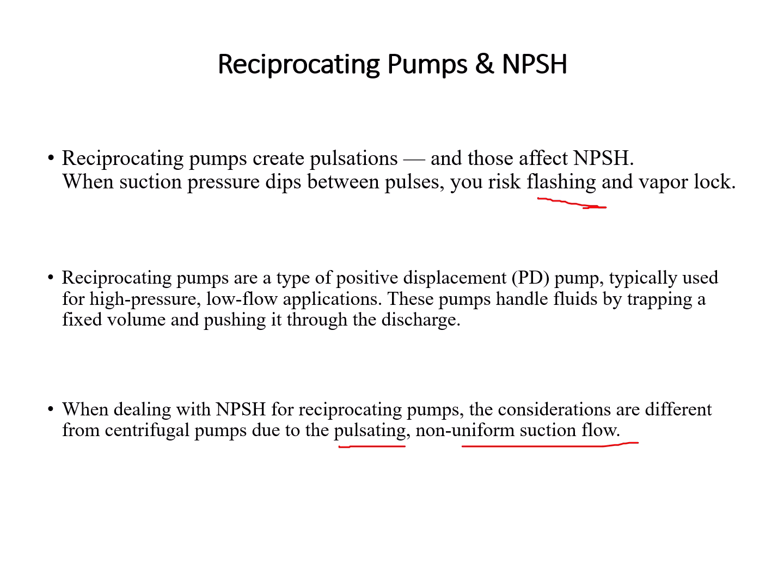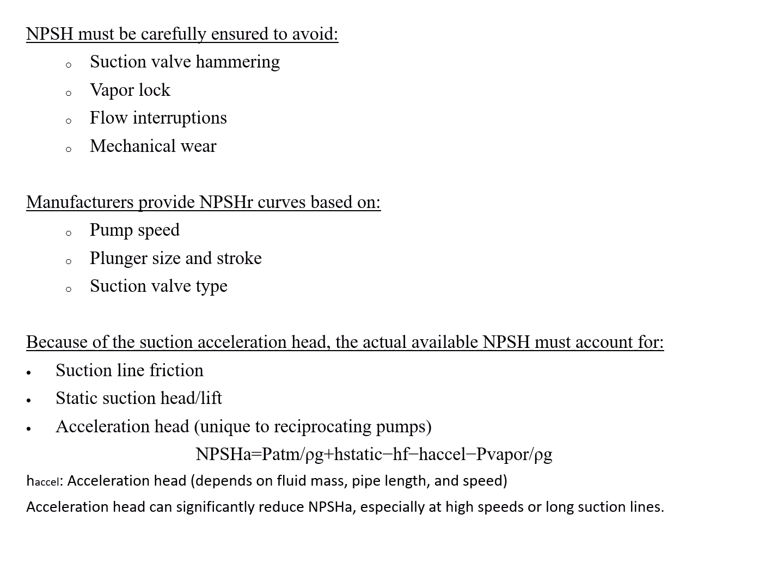Why? Because the piston itself is in acceleration. How? Because it starts from zero velocity, reaches the maximum velocity at the center of the stroke, and eventually decelerates from the maximum velocity to zero when it compresses all the fluid to the suction valves, and the suction valves will open. This means that there is an acceleration here. That's why the flow is not uniform.